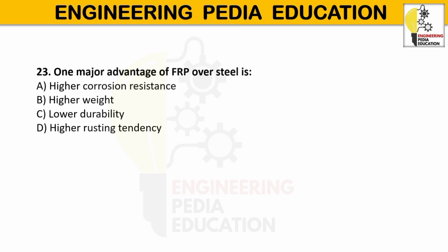However, FRP is generally more expensive initially and has lower stiffness than steel. Unlike steel, many FRP products do not yield before failure, so their design requires special consideration.